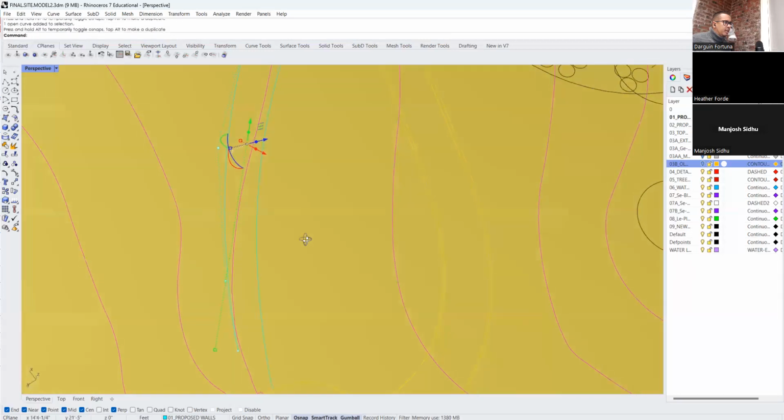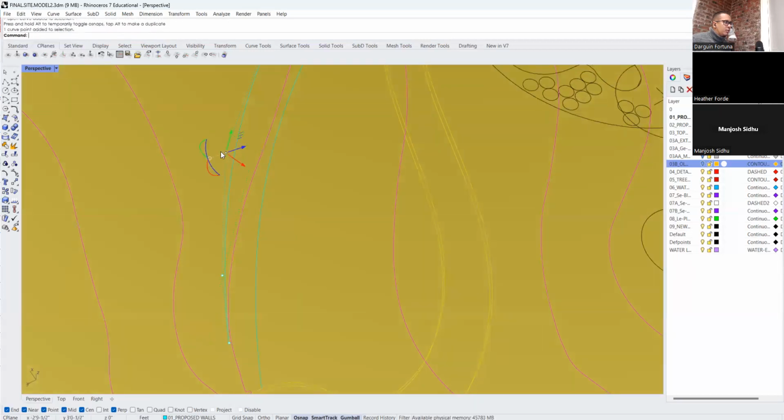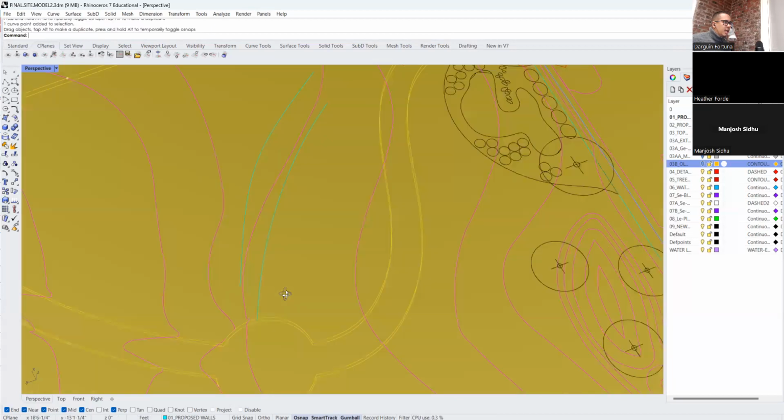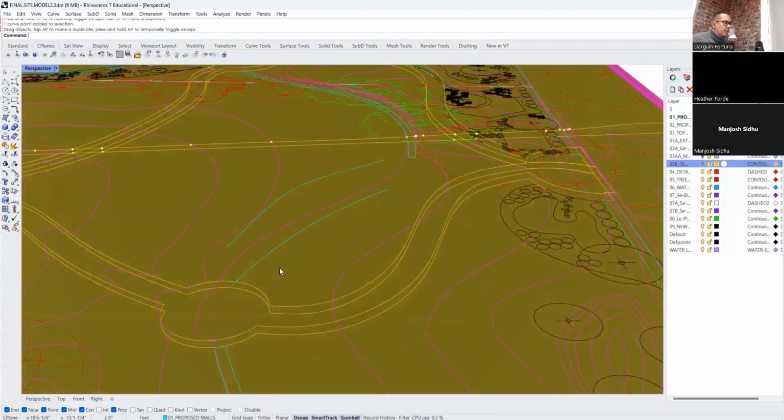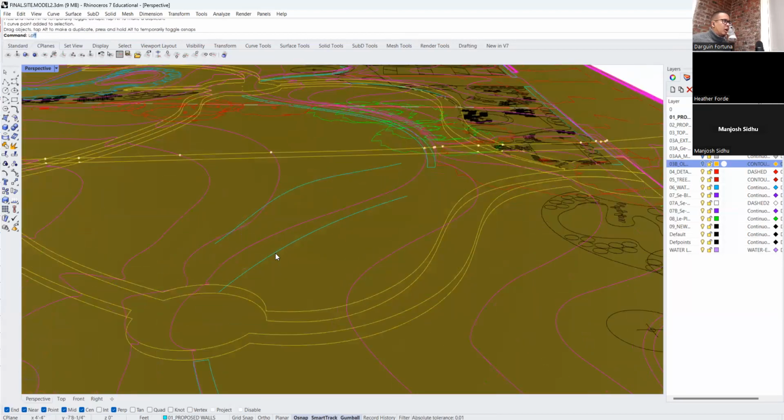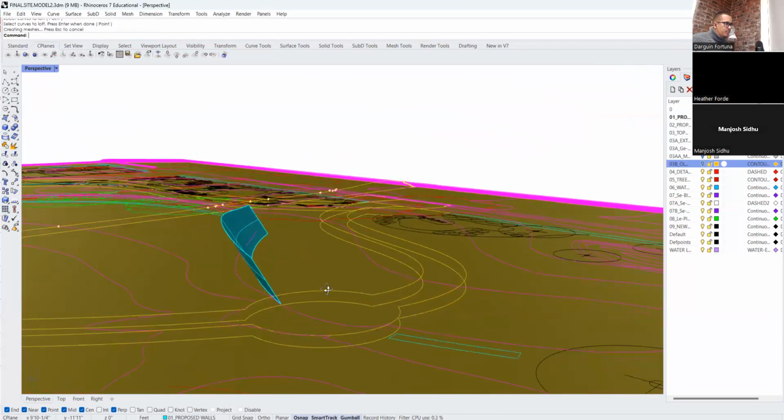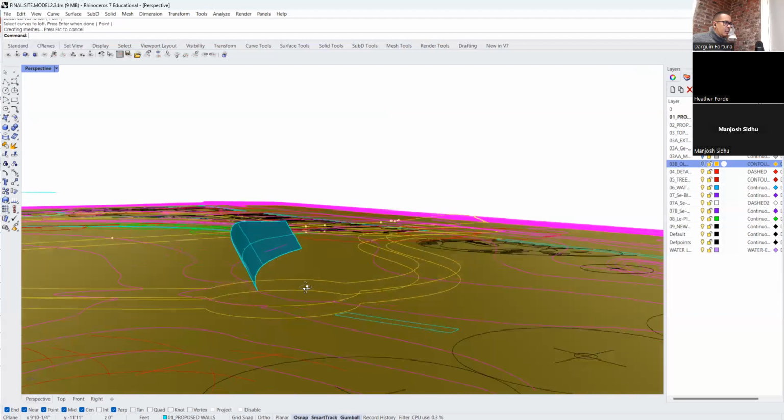Sometimes in plan is better so that it tilts back, but also you want it to be a little bit more exaggerated than what it is. And that's already done. That's fine. And then we're going to loft it. Loft. So you pick one edge, pick another edge, and then click enter. And it creates that for you right there, where it's being tilted back, right?